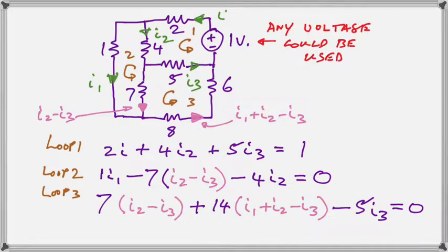So we are going to put a voltage source across A and B, and then find the current flowing. Then we're going to divide the voltage by the current, and that will give us the resistance of the network, which is our RTH, or Thevenin resistance.